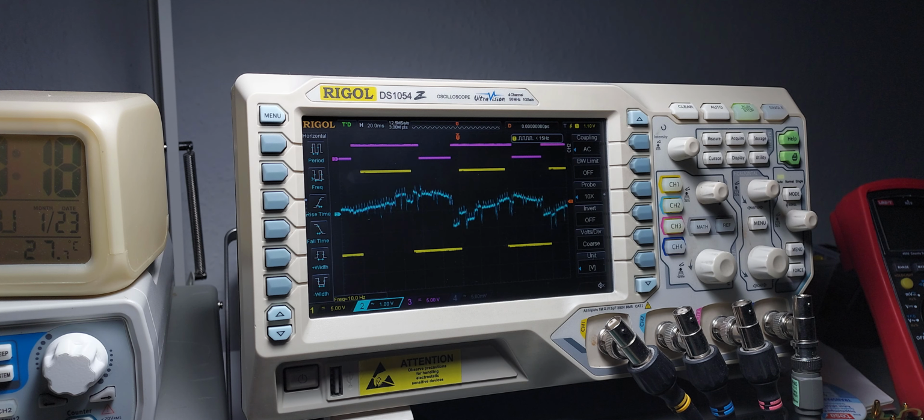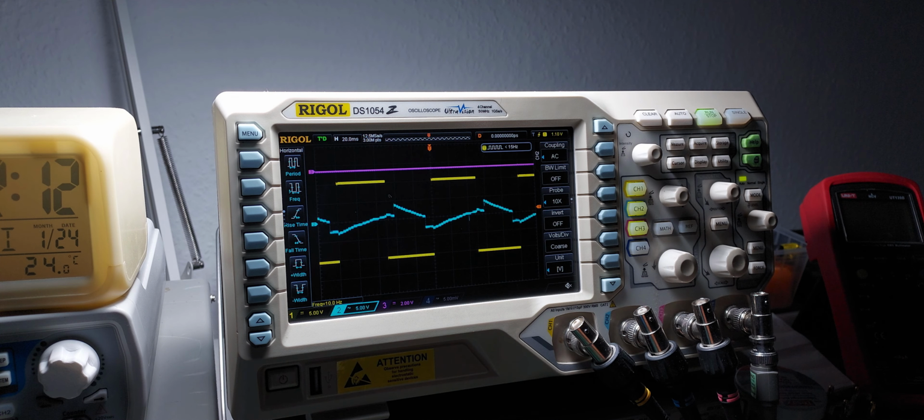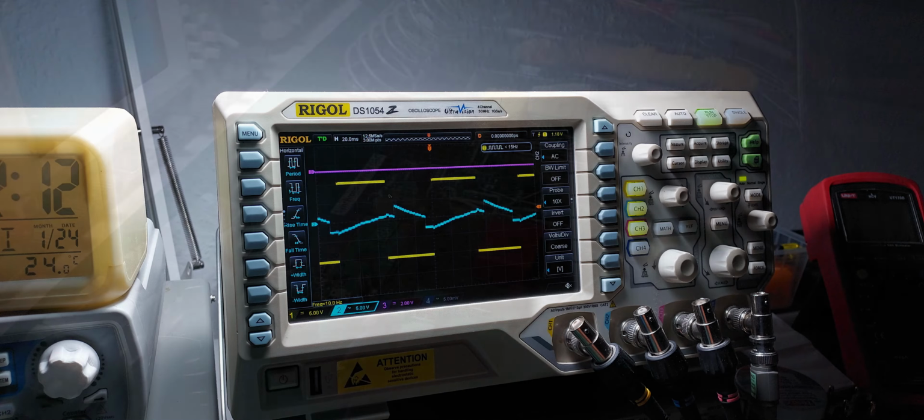But if I change the duty cycle of the sample and hold signal, it's clear that the sudden jumps in the waveform are a result of the sampled architecture. Even smaller capacitors make the ripple worse, and touching the sample capacitor injects some mains noise into the sensitive junction and demonstrates how choosing the right frequency can reject it.